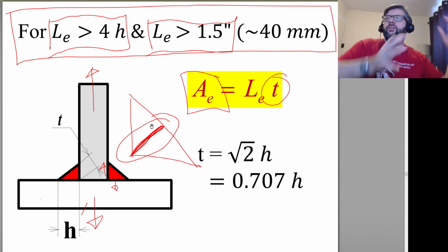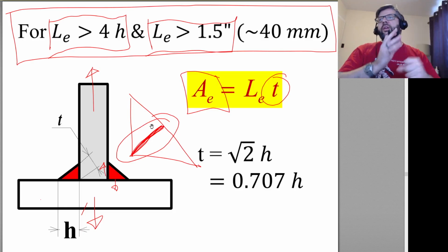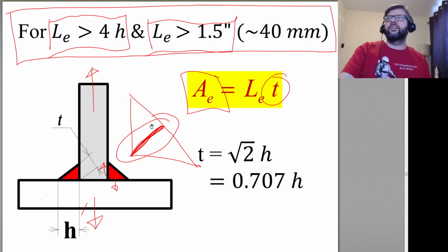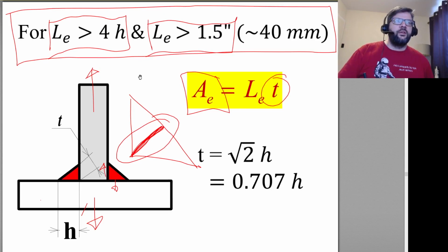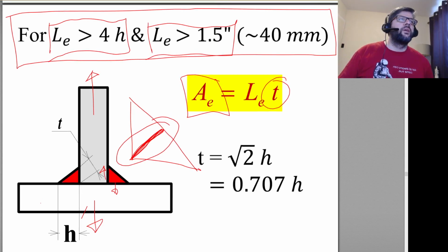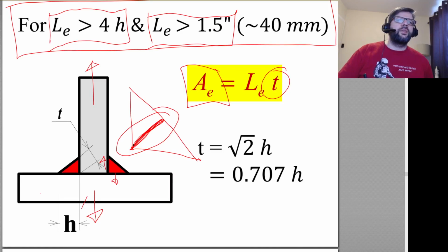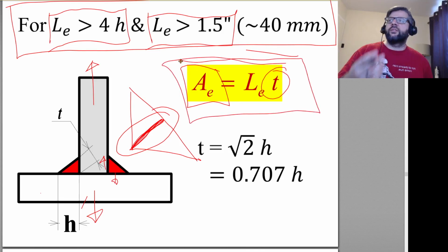Once you convert everything, do your Mohr's circle, compare your principal stresses, and rotate your frame of reference, you're going to get yielding at that point. So we calculate the area of that cross section times the length, and then we assume that the entire force is being carried in shear by that cross section.